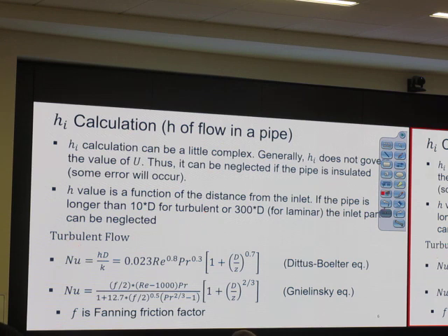The physical meaning of Nusselt number is the comparison between heat convection over heat conduction. If Nusselt number is more than 1, this means we tend to have convection better than conduction. For laminar flow, Nusselt number is about 3 or sometimes 4, far away from the inlet.